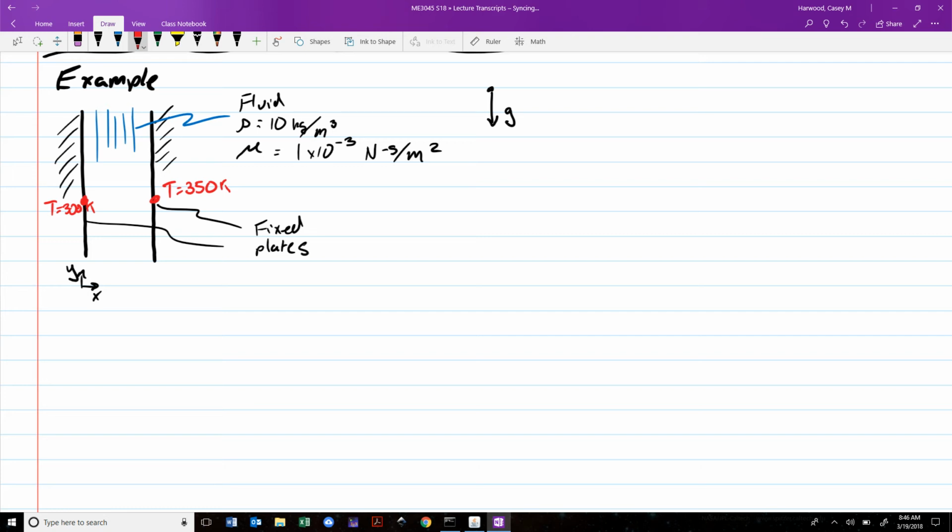It's a type of heat exchanger. They use these in a lot of industrial processing settings, on ships, and in water treatment centers. These are called plate type heat exchangers, where you have a bunch of parallel plates stacked together vertically, and you set some hot fluid flowing past one side and a cold fluid flowing past another. As the name implies, you want to get some of the heat from the hot fluid to the cold one.